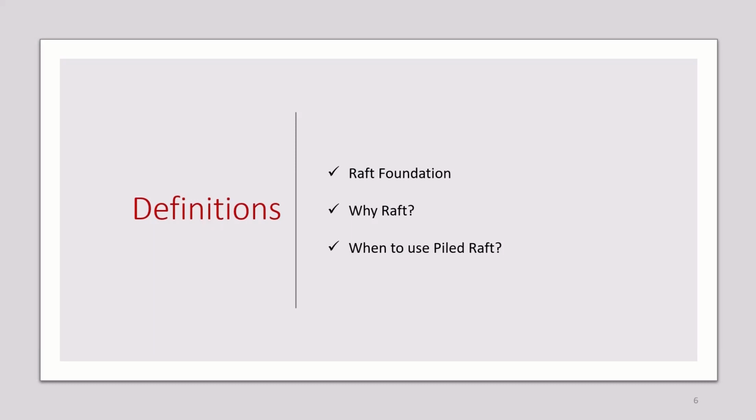When should a Raft foundation be used? Raft foundation is constructed on weaker soils that are poor with respect to the bearing capacity. Like a place in Lagos, especially like the islands, in some of the areas it's very difficult to use conventional shallow foundations, pad foundations, because the soil is not so good. You can also use raft foundations when columns are closely spaced and pad foundations may not be suited.